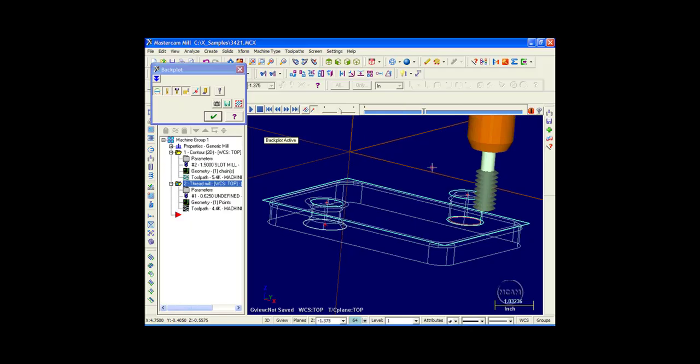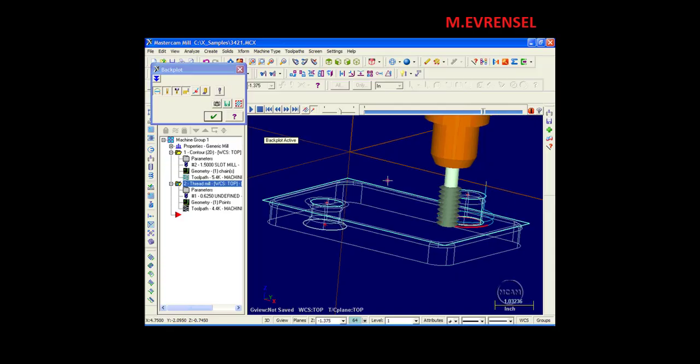Our end mill comes down, and depending upon how many active teeth we have told it that we have will depend how much engagement there is between the tool and the material. So it moves in, helixes down, and swings around, finishes, exits, and comes up again.